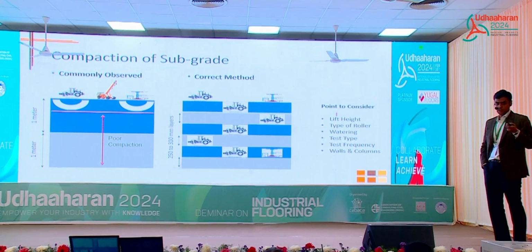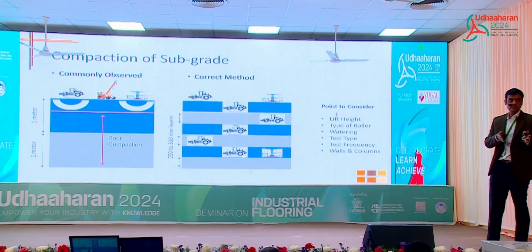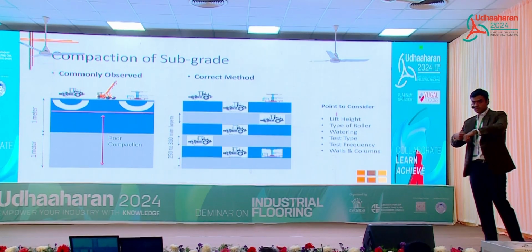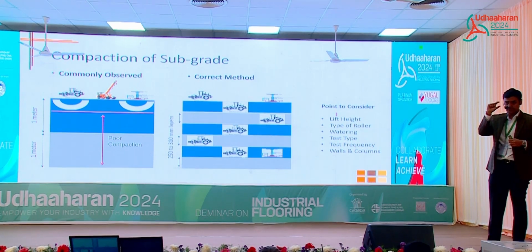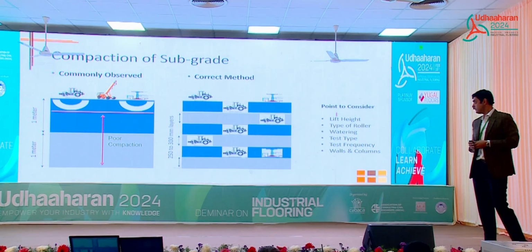Typically plate load is one test per 1000 square meters. Walls and columns should use a baby roller. The most common thing is to use a plate compactor. Again, it limits the compaction to 4 inches, but with a baby roller, you can have a larger bulb of influence.